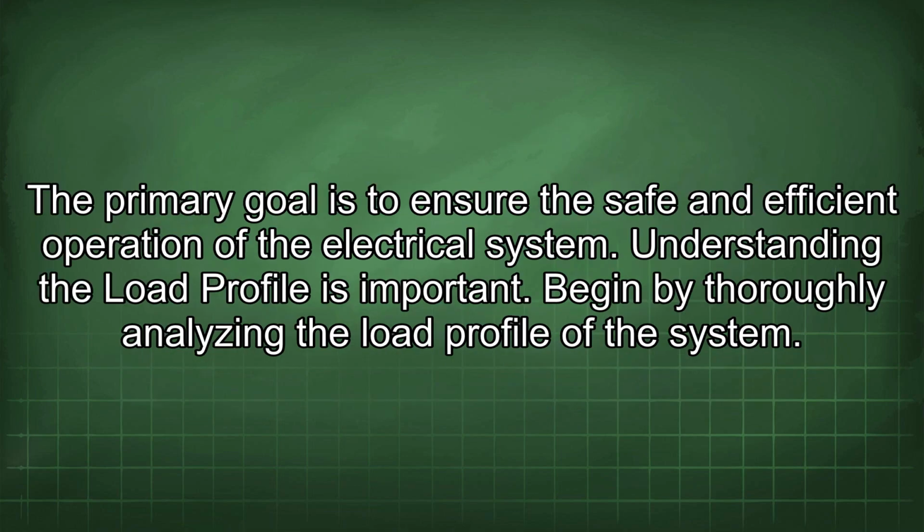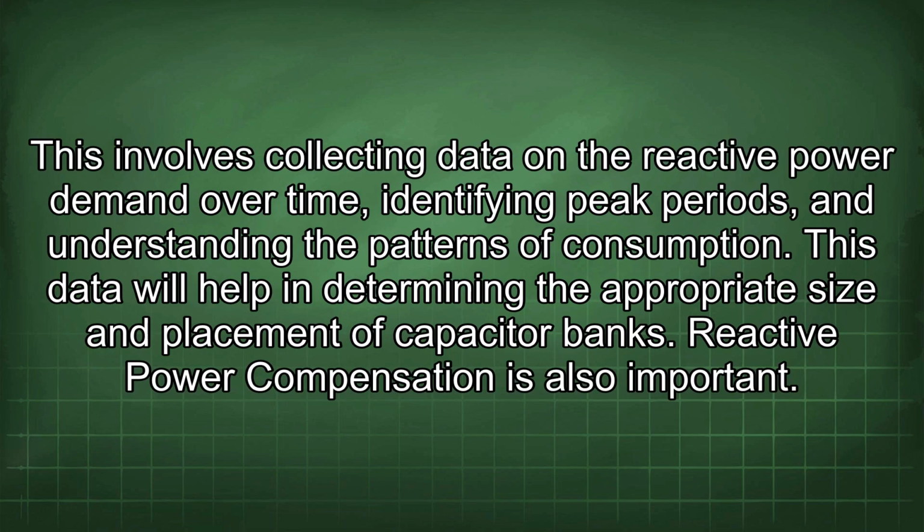The primary goal is to ensure the safe and efficient operation of the electrical system. Understanding the load profile is important. Begin by thoroughly analyzing the load profile of the system. This involves collecting data on the reactive power demand over time, identifying peak periods, and understanding the patterns of consumption. This data will help in determining the appropriate size and placement of capacitor banks.